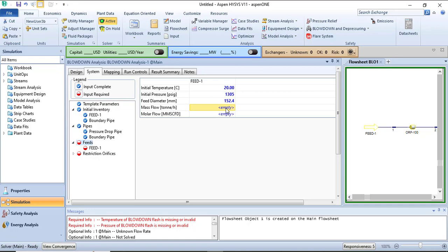And number three is because of that pipeline spool that I'm talking about, the bypass. So there will be a 90 and there will be a 0 and the valve open. There is a certain gradient of the pressure. So we have to check what velocities we are getting here, so that the piping team can provide adequate support to it. So these are the three things.